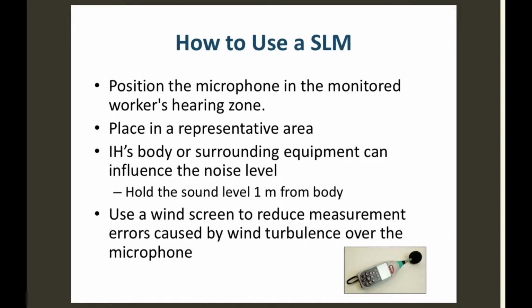And you want to use a windscreen because you don't want to measure short-term changes. Remember, the pressure of the wind is much greater than that little bit of pressure from the sound, so it can really impact the reading that you get. So literally, that is much greater than what my voice is. My voice doesn't produce that same effect.